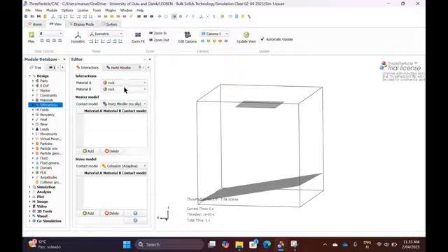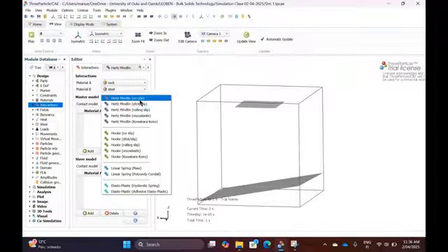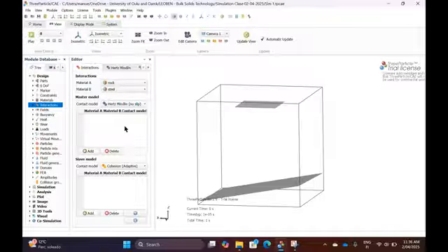I change material A rock, material B steel, or vice versa, doesn't matter. And I say which contact model, please don't look into that, just select the default one. There are lots of them, as you can see, predefined, and you can change any of them in detail, but let's just add the default contact model, dry Hertz-Mendel no-slip contact. So we say, contact between rock and steel, defined. No slip model, no stickiness, no cohesive behavior, just dry material rock to steel.